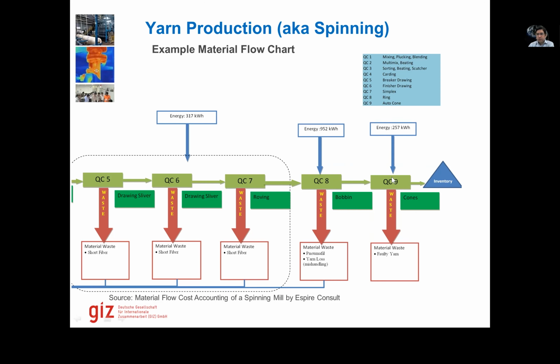In the auto coning process, there are a lot of very small pneumatic cylinders which are operated using compressed air, and usually many of these are leaking, especially their connecting pipes. So normally they can be fixed only by pressing a little bit, but with the passage of time, there's heat generated mechanically in the process, so these actually become brittle with time, and then we have to replace them. So this is what the process is about.